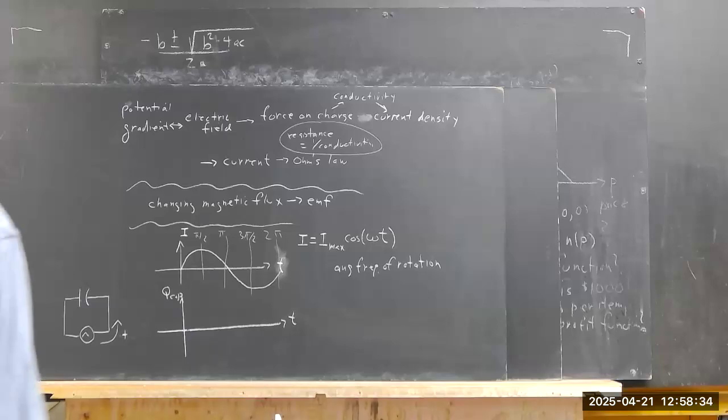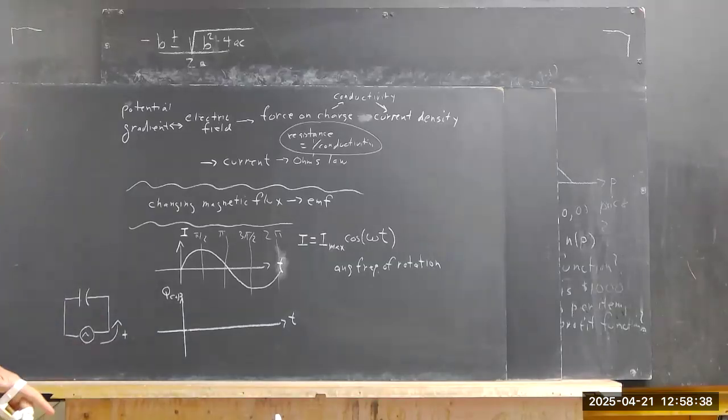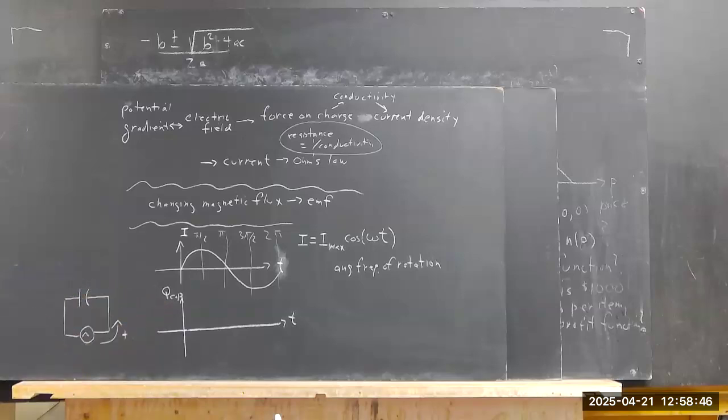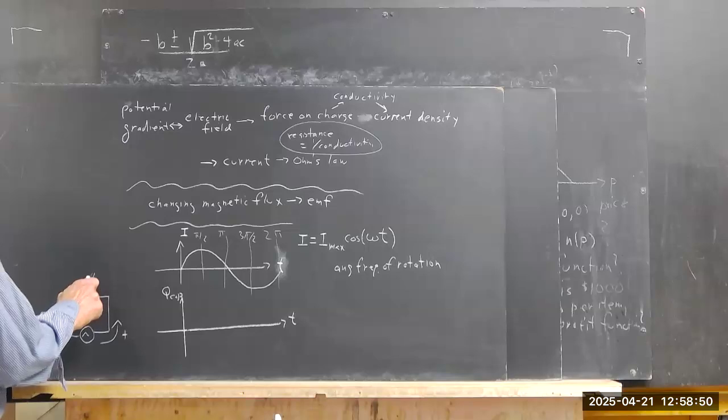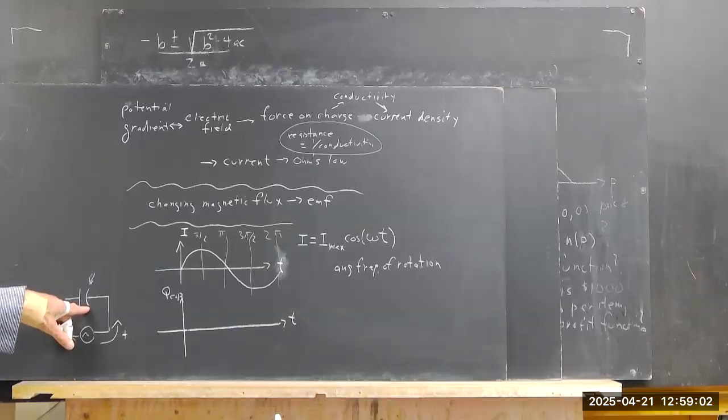Okay, now this might cause us to have to reverse our thinking, and I didn't make a decision on this earlier, and I should have, but I'm going to say the charge in the capacitor is the charge on this plate right here. Okay. So if the current's flowing this way, this plate is going to be positively charged, right?